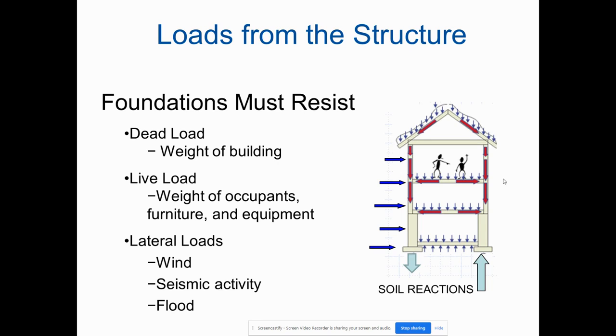Those are the design considerations. Foundations must resist dead load, which is the weight of the building and all the fixed equipment; live load, which is the weight of the occupants, furniture, and equipment that's not necessarily bolted down or a permanent part; and then lateral loads such as wind, seismic activity, and flood. So this is the way soil reaction works. All the weight gets transferred from the support into the foundation, and then the foundation into the soil.